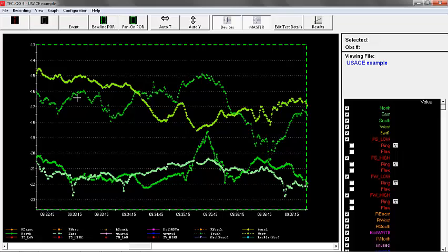So we're seeing a difference of a few pascals between levels of the floor, but then we've also got a pretty big wind variation that you can see. So if we chose just one of those, you can see how much fluctuation we'd have on our envelope pressure.